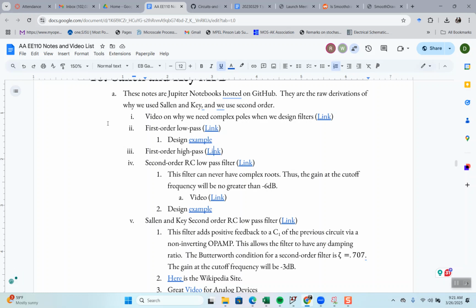Okay. And so, really, I like above 10K, but the data sheets are like 2K. So if it's around 2K, all right. But if it's below that, I've seen circuits not work because the op amp can't drive the current. So then that's not realistic. That being said, people tend to knock this problem out of the park.